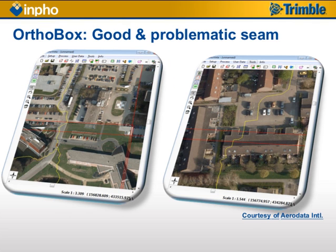But just enhancing the automatic capabilities is often not enough. On this slide, you see some examples of a good and a worse seam line. The good seam line, of course, has to avoid the buildings, it has to avoid the cars on the streets, and so on. On the right side, you see a seam line passing through a building, and these are, of course, usually areas where you need some manual editing.